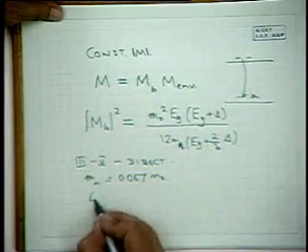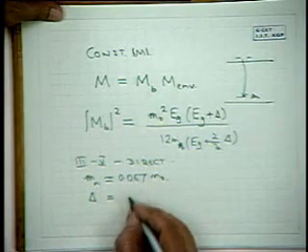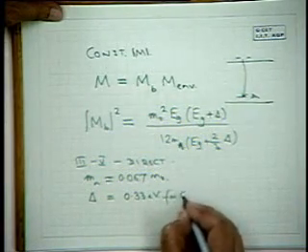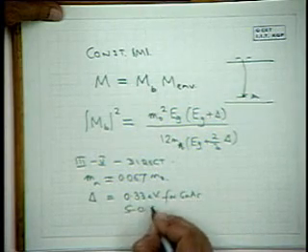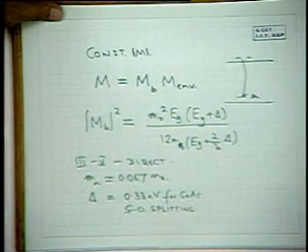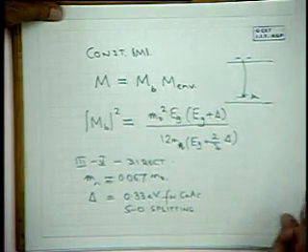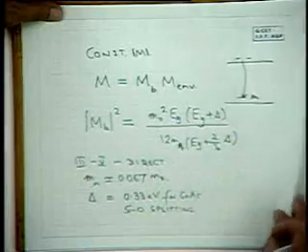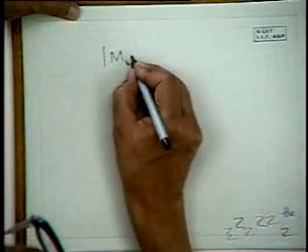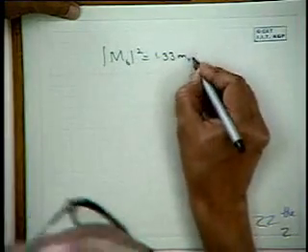What is delta? Yeah, spin orbit splitting. So that is 0.33 eV for gallium arsenide. And Eg is the band gap of gallium arsenide. And one can write this as Mb squared, simplified as 1.33 M0 by Eg.